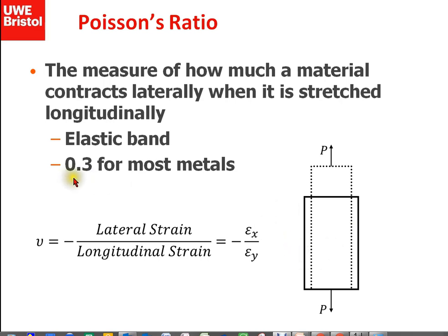If it did, actually, the Poisson's ratio would be equal to 0.5. But for most materials, we get values below 0.5. So we get values of 0.45 for rubber. So when I pull rubber apart, typically the volume stays pretty much the same. So you get values heading off to the 0.5 value that I'm talking about. Whereas for metals, this effect loses its volume a bit more significantly, and for most metals we have a Poisson's ratio of 0.3.